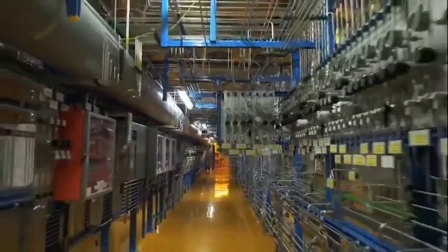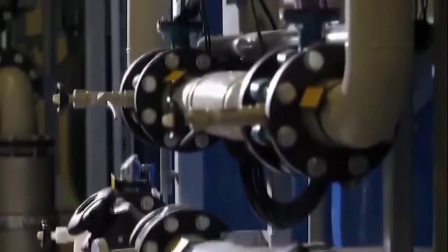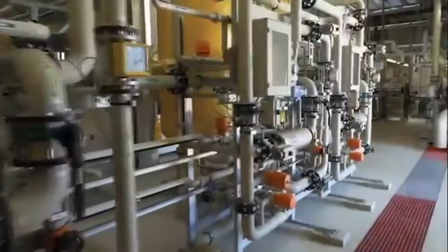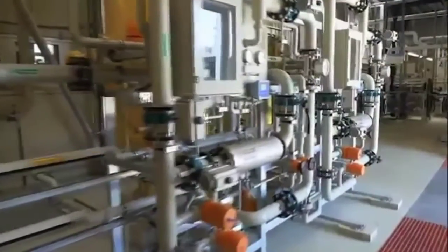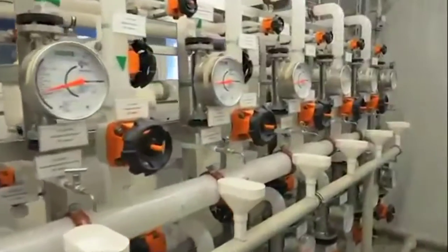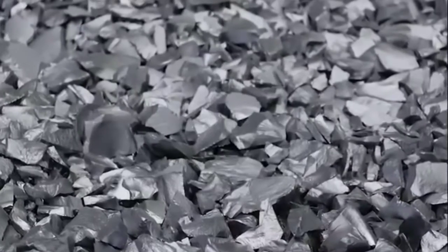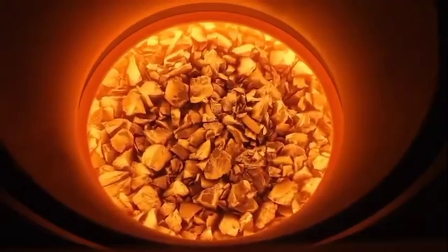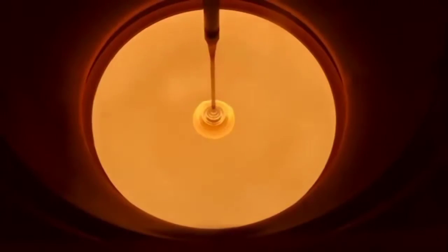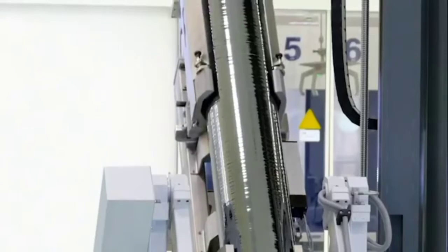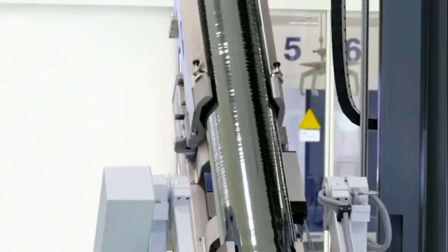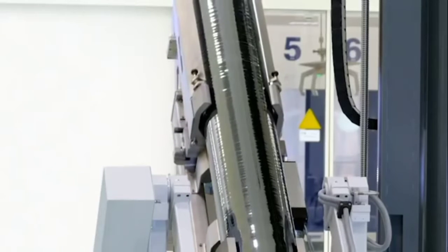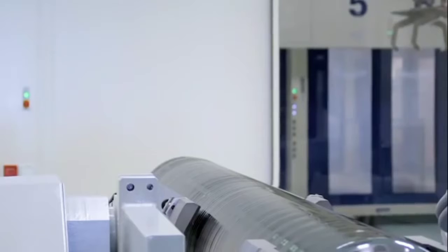Complex chemical and physical processes are required to ensure that silicon crystals meet the high production standards that apply to chips. To convert silica sand to silicon, the sand is combined with carbon and heated to an extremely high temperature to remove the oxygen. A number of other steps are required to create the finished product, namely an extremely pure monocrystalline silicon ingot called a boule, with only one impurity atom for every 10 million silicon atoms.